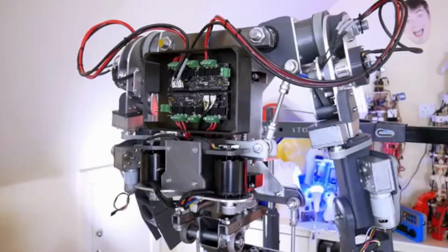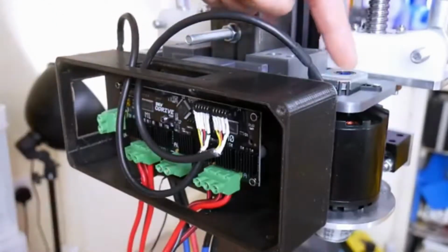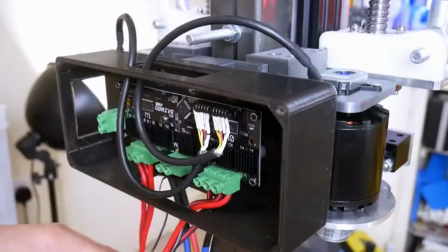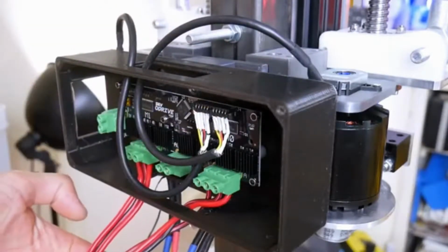Those go to the O drive. Yep, that's the same down the bottom. So we've got the encoder on the back of the motor with an encoder cable that I've made the right length that goes to the O drive, and the power leads come out the bottom to the bottom of the motors.